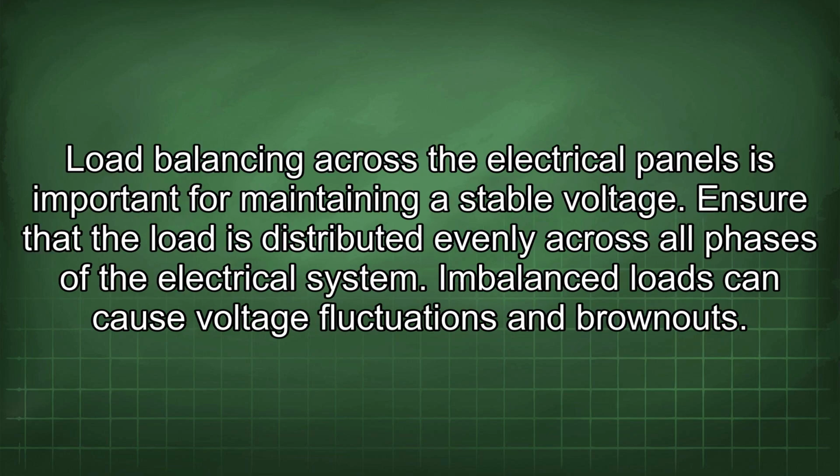Load balancing across the electrical panels is important for maintaining a stable voltage. Ensure that the load is distributed evenly across all phases of the electrical system. Imbalanced loads can cause voltage fluctuations and brownouts.